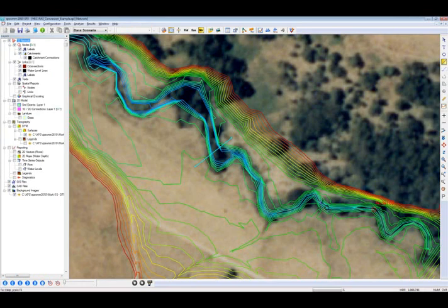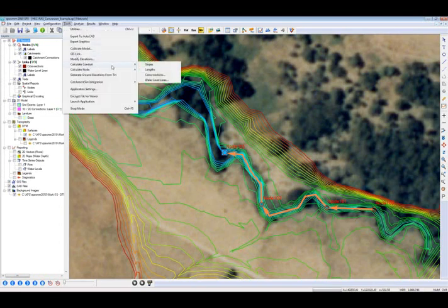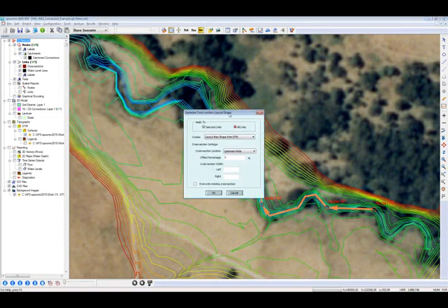our links. Now you can either draw straight links, or holding the control button, we can draw links with vertices. As you can see here, I drew a short river reach. And now, using the tools, calculate conduit cross sections, this option, I'm going to use for all links, and we can have the cross sections draped automatically, a percentage from either node. I'm going to have it be in the middle, so 50% from the upstream node.